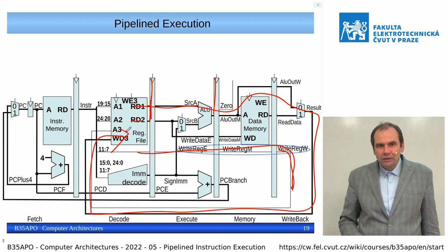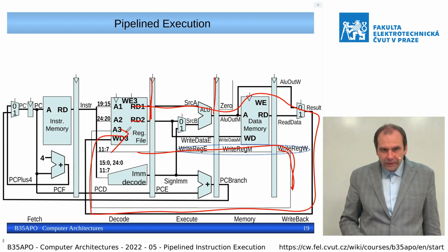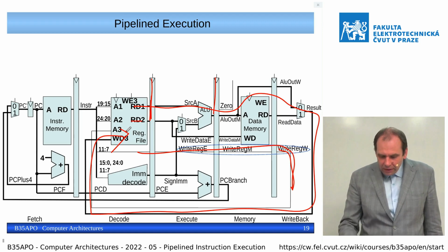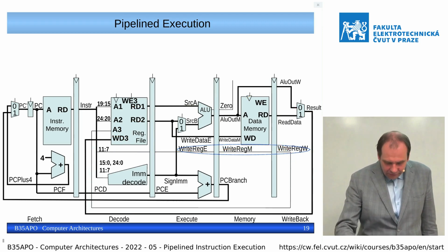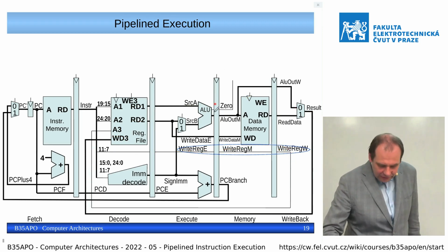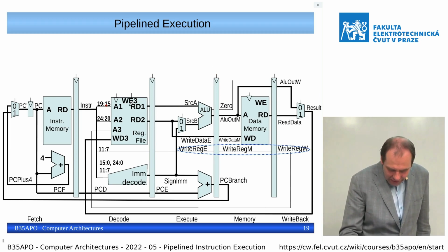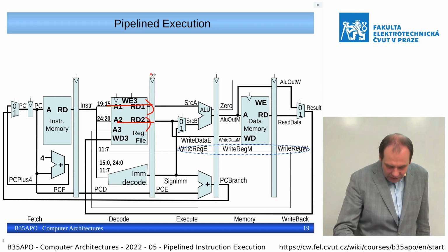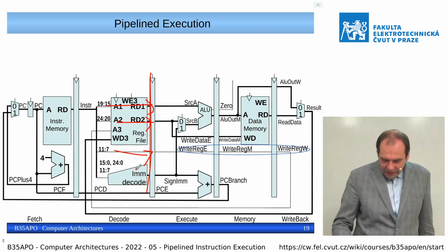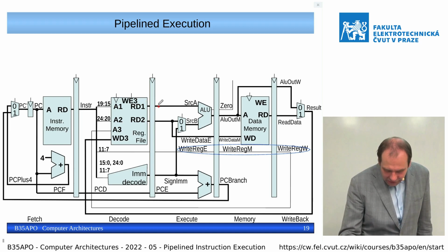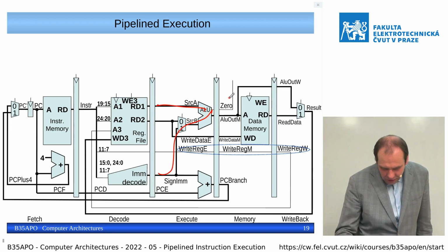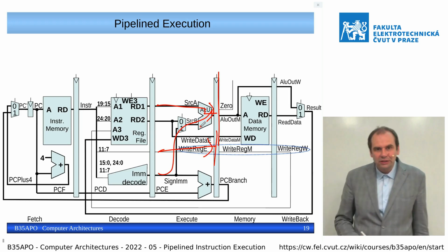So can you just repeat one more time what happens after it leaves the ALU? After the data leaves the ALU, the data are stored here. So basically, in one clock cycle, we get to this interstage, and it is held here. Then on the next clock cycle, we compute from those values, for example, the addition, and we store the result here, and we again remember what the destination register is.